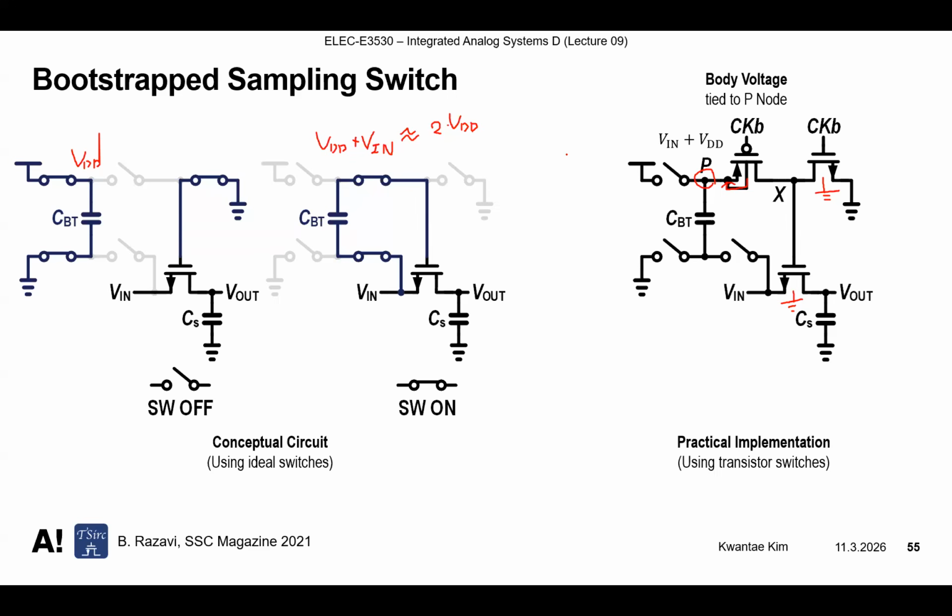But normally, when we say our technology's maximum supply voltage is 1 volt, if we plug in like 5 volt, then your transistor, your circuit will be dead. It will just blow up. That is the maximum voltage it can endure, it can tolerate. So that is specified for the VGS, VDS, and also VBS, the body to source voltage.